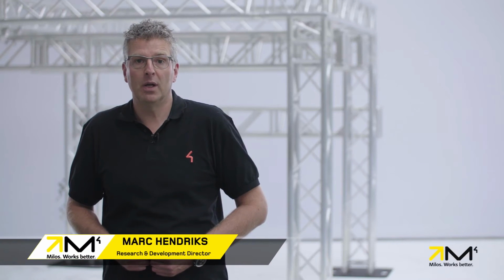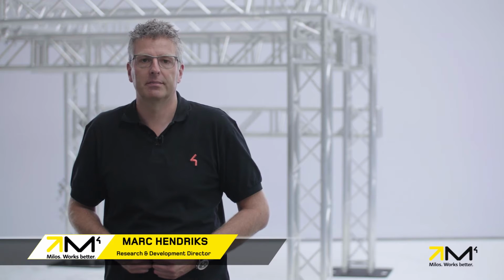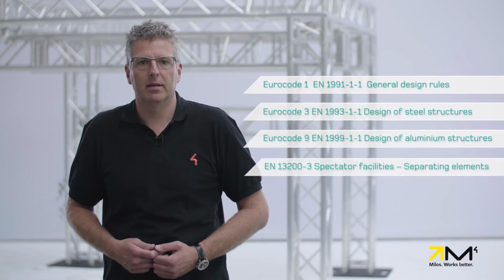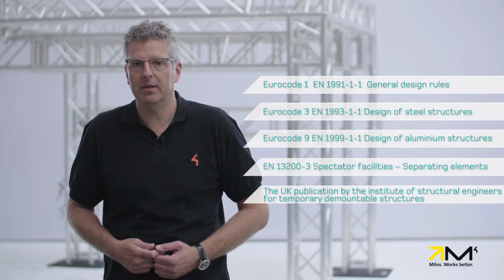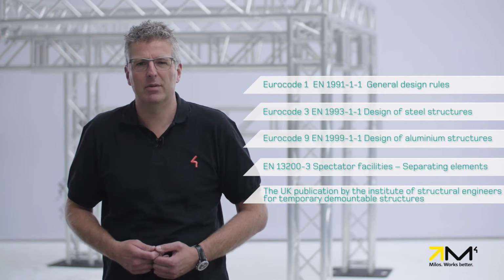In this video, we would like to give you a little background about the technical design of our crowd barriers. Despite what you might think, there are some regulations with which crowd barriers must comply. Some barriers on the market seem to be designed to conform to EN 13814, the European standard for temporary demountable structures. This standard, however, only covers handrails and not crowd barriers.